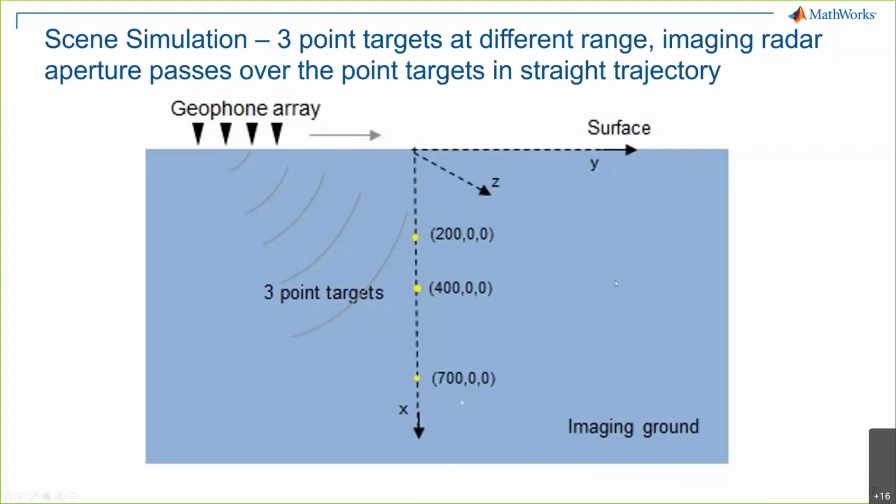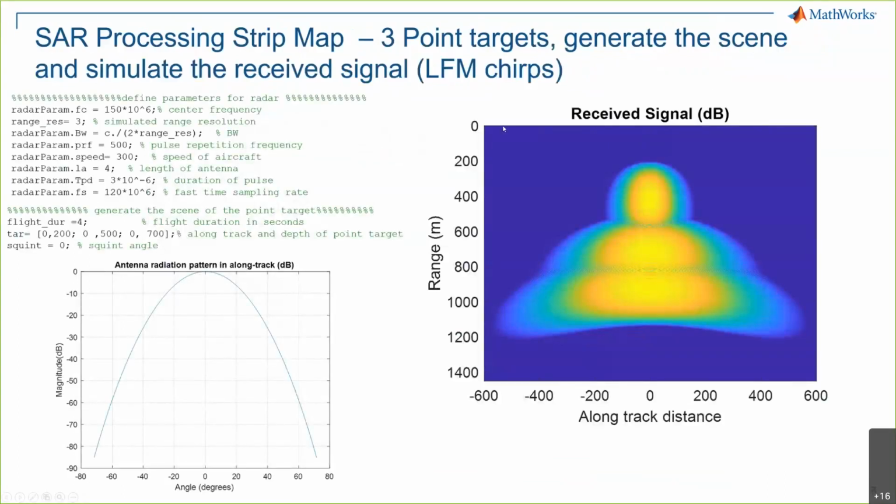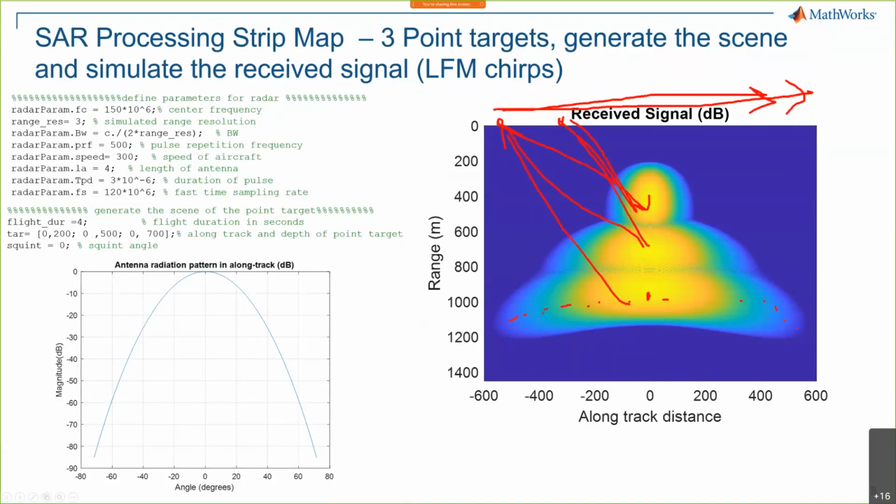So what that really does is once I collect the rays, because my ground penetrating radar is moving in this direction. So when my radar is over here, the signals get reflected back from the first target, the second target, as well as the third target. Then my signal, when it's here, gets reflected off the first target, second target, and third target. So basically, as it goes along this entire path, we get the return signals throughout. We get some intensity returns, and it's very strong in the center. It fades away towards the edges because of the antenna pattern.